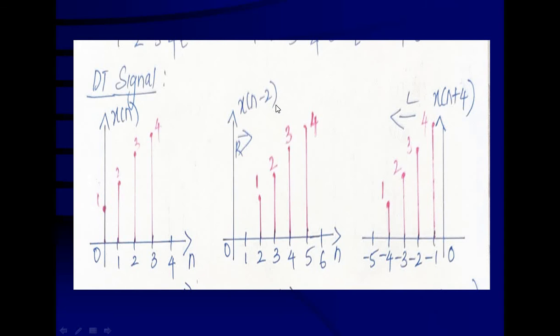So you will have to create a signal called x of n minus 2. This is a delayed signal, so simply shift your entire signal towards the right side. Remember, we are not going to alter the amplitudes, we are just going to glide the signal. So changes will happen only in the x-axis and not in the y-axis. The signal shape or structure is never going to get altered. So we'll have to give 2 time units shift. The signal starts at 0 and ends at 3.